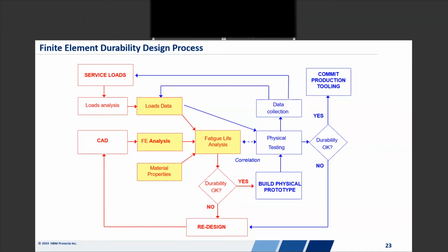At that point, we end up going off and usually building that component and testing it. Here on this chart is showing that we build a physical prototype, which is a bad thing in terms of fatigue testing, because among the other things that affect fatigue performance, the manufacturing of the component does as well. And so going off and building a prototype, not following exactly the same manufacturing procedures that the final product is going to use, may not capture all the fatigue performance, good or bad.